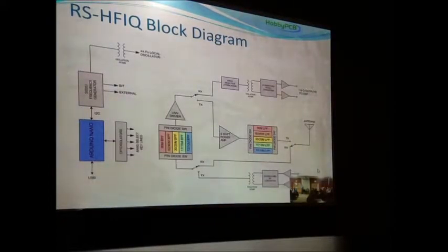Our frequency generator is the Si5351 from Silicon Labs, and it takes a 25 megahertz clock. It's a little teeny tiny chip, and you can program it to make any signal from 4 kilohertz to 225 megahertz. And the library we're using in the Nano gives you control to 0.01 hertz steps. Now, my control function only uses 1 hertz steps because it was getting a bit ridiculous, but it's really an amazing chip. It has 3 outputs, so we're using 1 to drive the local oscillator at 4 times the frequency.